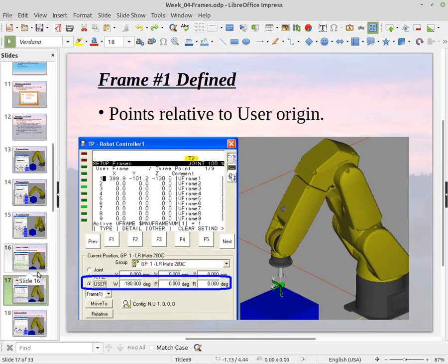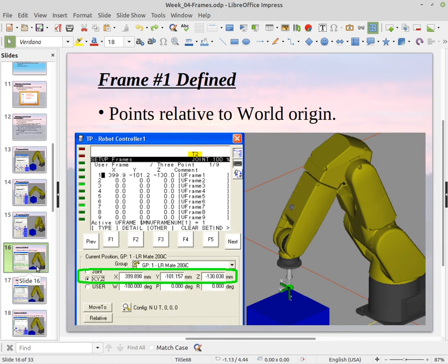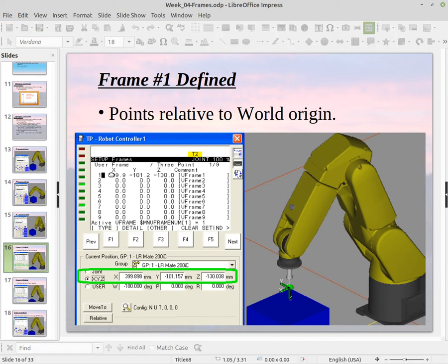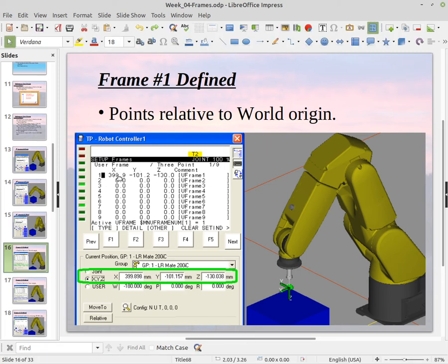So anyhow, this slide here is showing the XYZ. This is again just in Robo Guide. We can't actually see this on the Teach Pendant. This bottom part that I highlighted here is only for Robo Guide software, but it's showing you XYZ, which is basically the world frame, and it's showing you that the user frame is defined, as I mentioned before, based on the world frame origin.